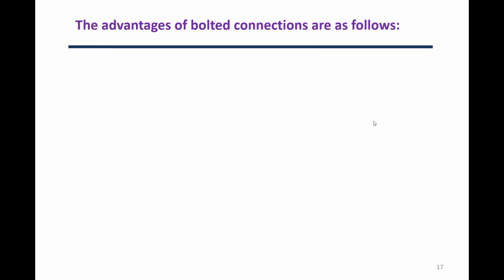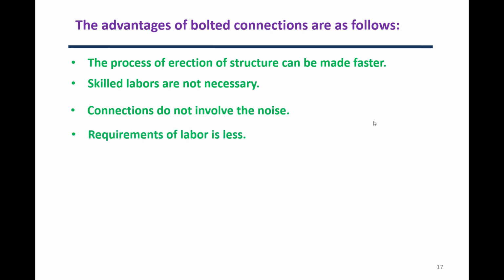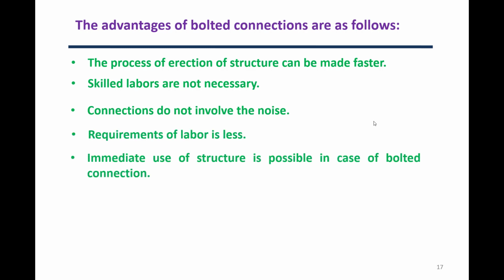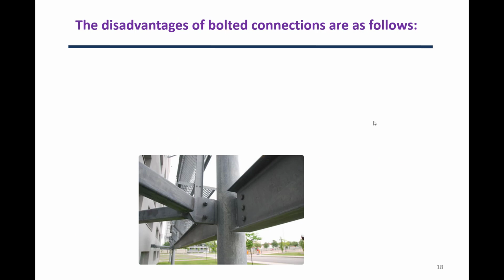So the advantages of bolted connections are as follows. The process of erection of structure can be made faster, so skilled workers are not necessary. Connections do not involve noise. Requirement of labor is less, so immediate use of structure is possible in case of bolted connections. Alternative arrangement of structural members is possible if required. Lesser working area is required.